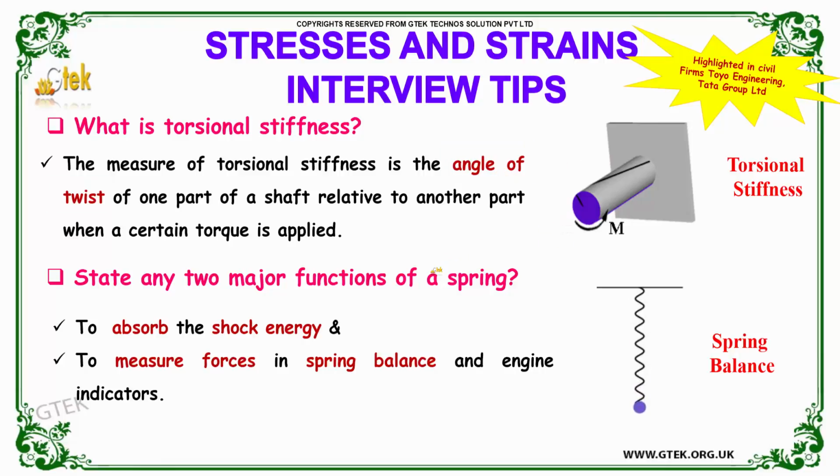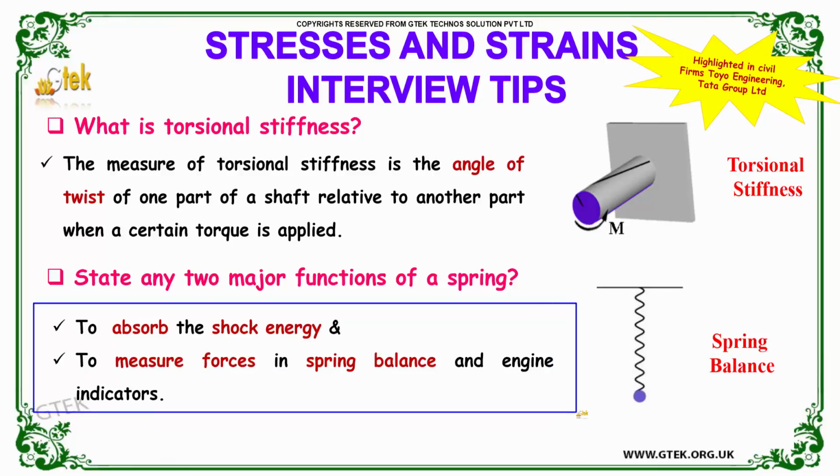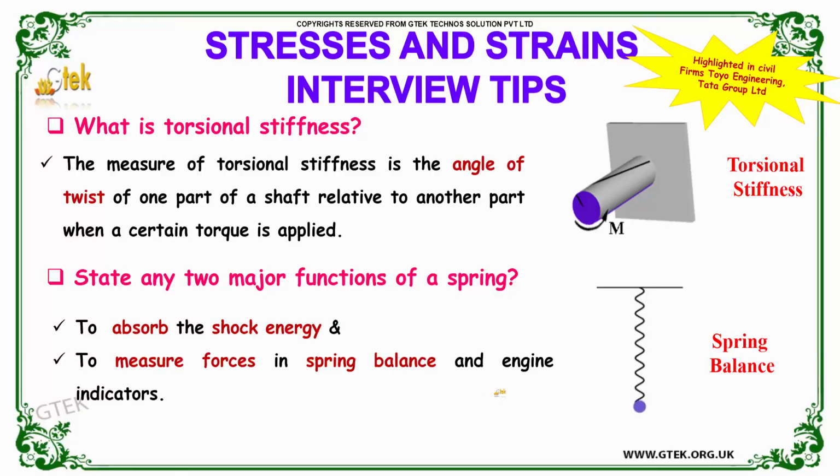Our next question is, state any two major functions of a spring. Some of the major functions of the spring are as follows. It is used to absorb the shock energy, and it is used to measure forces in spring balance and engine indicators. So this gives the major functions of a spring.